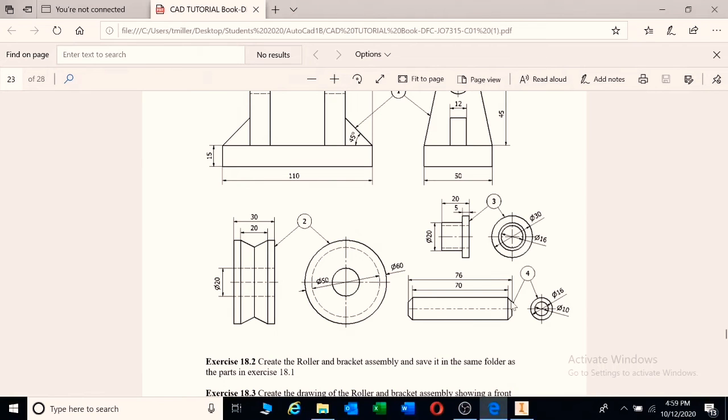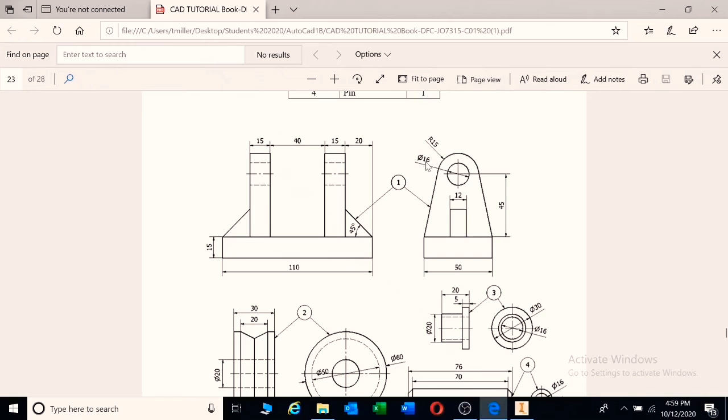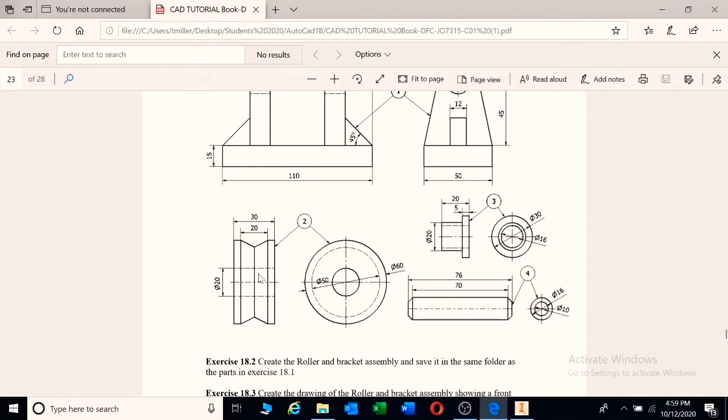It's a 3mm 45 degree, because we can see the difference in the diameters is 6. It's also 3 and 3. So based on this, we have a diameter for the shaft of 16. So that 16 will go through there, because it's the only 16 that can fit through these holes.